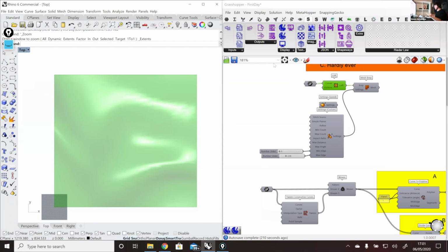Then you have to, of course, try it out and see if it's the most optimal way. Maybe there is another way, but that, for example, is a solution. Instead of using the Boolean operation, you would use the projection and the split surface operation instead of the Boolean, which is more computationally expensive. Then you can try it out, iterate, and try to find better and better ways to do it. Any other question?